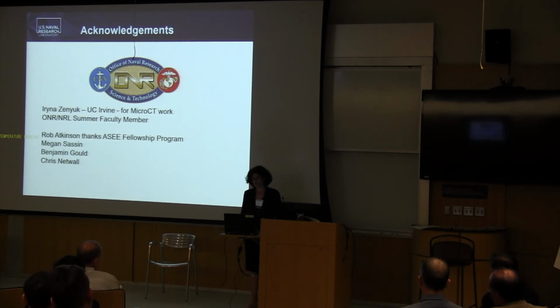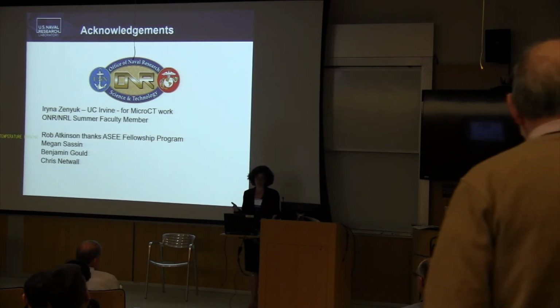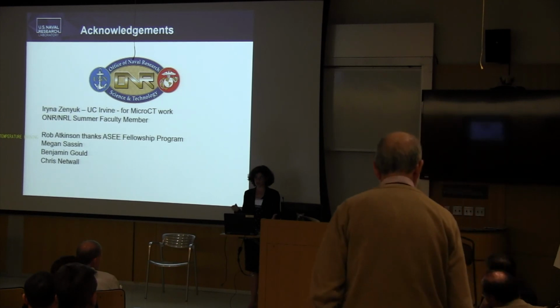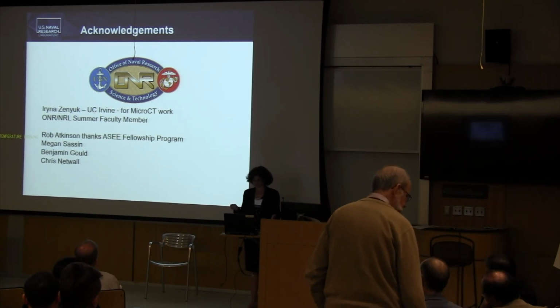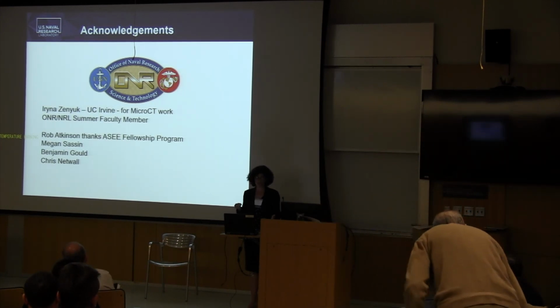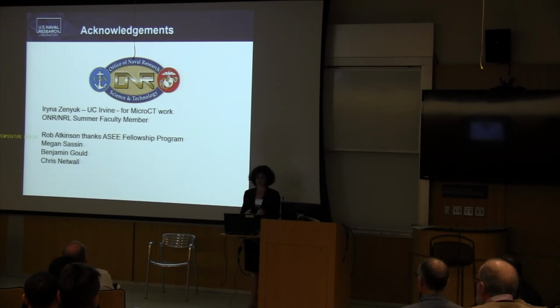But I think it also depends. We only look at 80 degrees C. We look at 40 degrees C in different relative humidity. So I can't say which gas diffusion media is better for startup or things like that. You'd have to get in and look at it. But the point is that it'd be nice for people, when they talk about their membrane assemblies, to at least report the gas diffusion media, the compression, and take a look in your own lab.